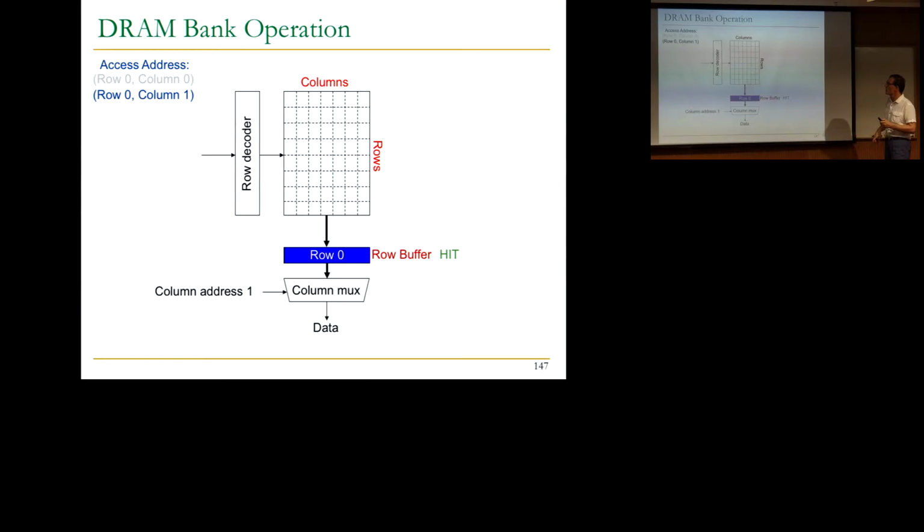So in this one, you could pre-charge, but your anticipation may be that I'm going to get another access to this row because of spatial locality. A lot of the memory controllers have that anticipation. But if your anticipation is that I don't have any spatial locality, you can pre-charge immediately so that you can save time. That's called a row buffer management policy, and we will talk about that also. Make sense? Another question over here? Okay, good. We'll talk about the row buffer management policy in a little bit.